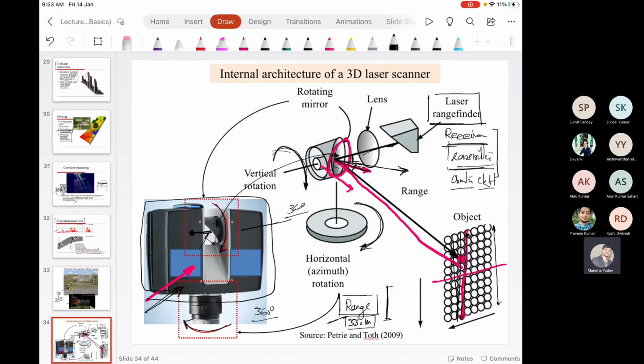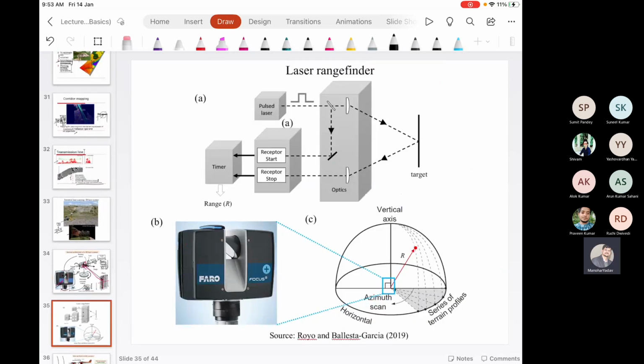Okay, so this is the basic operation that talks about how, when you initialize a LiDAR system, a TLS over here, after the initialization it acquires the points' coordinates in its surrounding up to the maximum range that is given for that particular instrument. Okay. Now we'll see the working of a laser rangefinder. What are the internal components of a laser rangefinder?